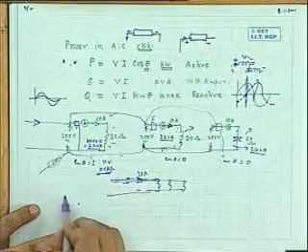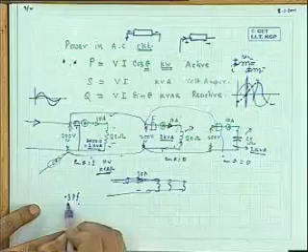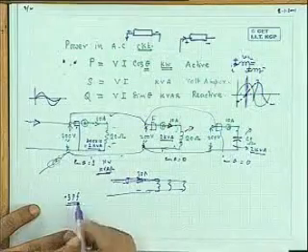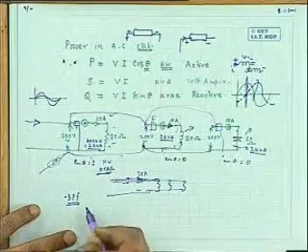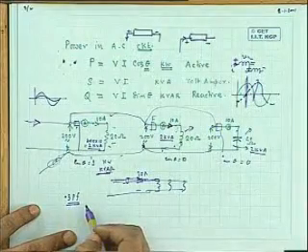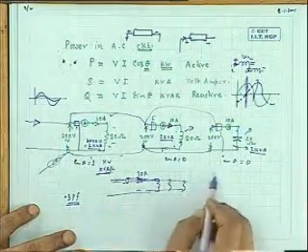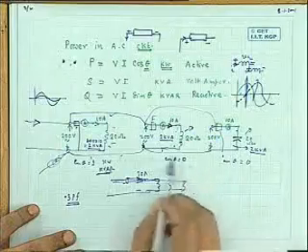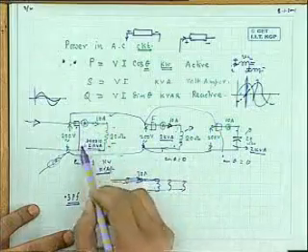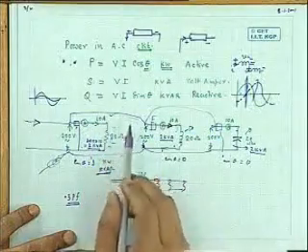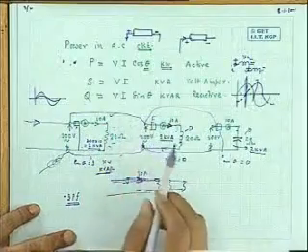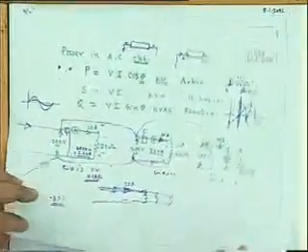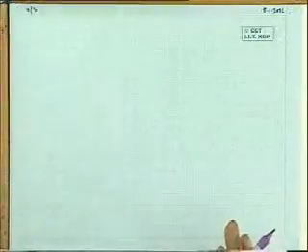In fact, for big industries they do it like that. Any industry drawing power at say 0.3 power factor will be highly penalized for their reactive power. So in AC circuits these things must be understood. You calculate the active power and the reactive power.